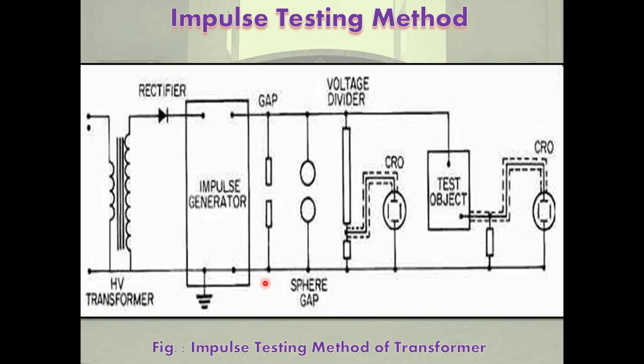Now, direct and alternating voltage. The voltage with a low magnitude is applied so that the transient switching surge voltage does not cause disruptive discharge. The voltage is increased gradually so that the voltage at which the disruptive discharge occurs can be read correctly on low voltage indications. Alternatively, a constant voltage is applied across the gap, and the spacing between the spheres is slowly reduced until disruptive discharge occurs. The final measurement should be the mean of three successive readings, agreeing within 3%.